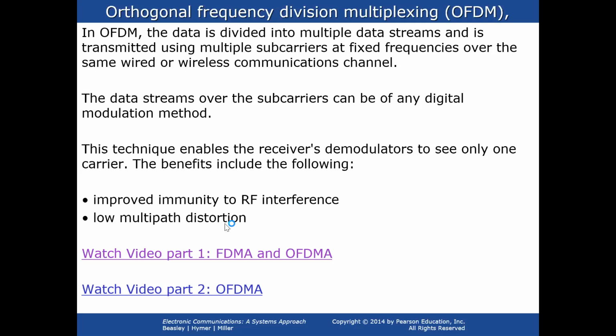In time domain, these subcarriers will be represented as everlasting sinusoids at these carrier frequencies as shown. However, in order to transmit data over these subcarriers, they are loaded with modulation symbols that represent the constellation points of digital modulation schemes, like QPSK and 16QAM. Also, the symbol duration for each of these subcarriers is always equal to 66.7 microseconds, which means that all these subcarriers have a whole number of cycles in one symbol duration.